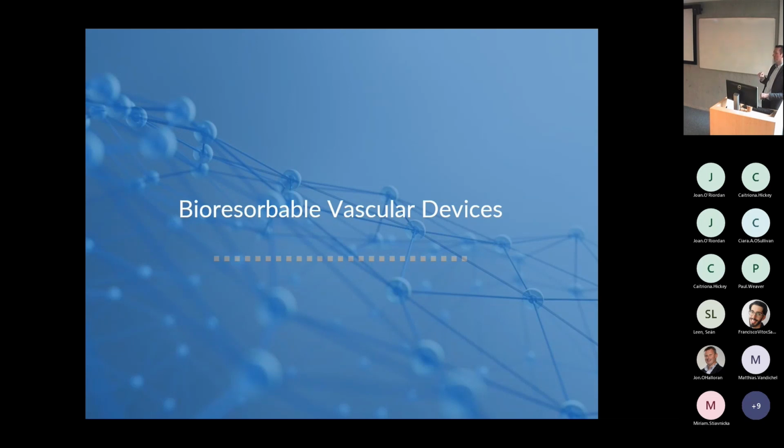As we scale down to something that's 150 microns, in terms of a stent strut, our pit size detection had a resolution of 50 microns. So we probably wouldn't have the resolution for that, and we'd have to go to a higher resolution if we were scaling down. So maybe do some crystal plasticity.